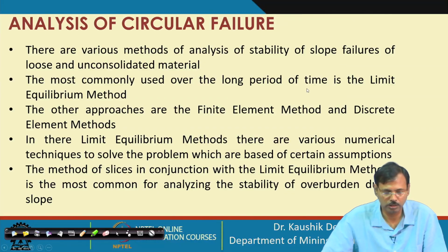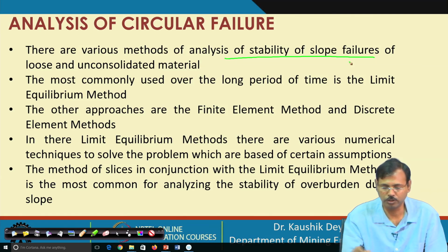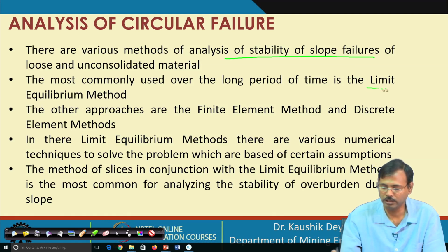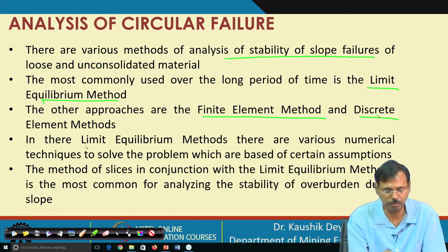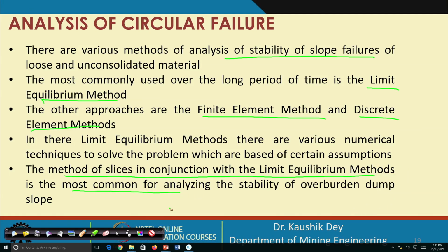So, now look into the details of this circular failure. For circular failure, there are various methods to analyze the stability of a slope. One is the limit equilibrium method. Apart from that, finite element methods, discrete element methods, and Bishop's analysis are also there. The method of slices in conjunction with the limit equilibrium method is the most common method for analyzing the stability of overburden dump slopes. So, let us have a look at this.